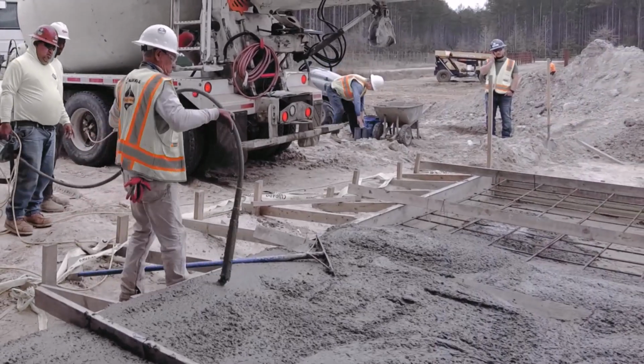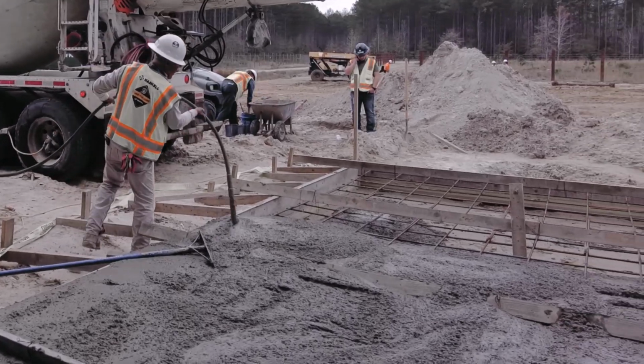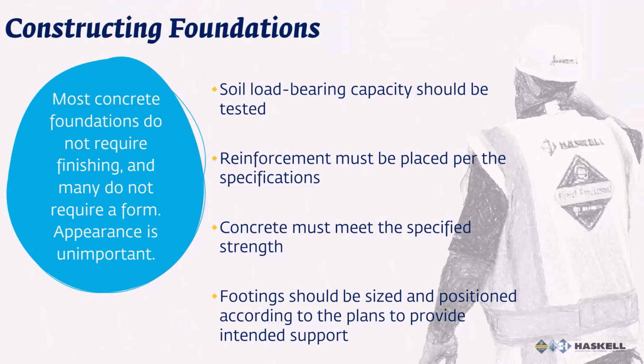Concrete foundation work is different from placing and finishing slabs. Since footings are normally below grade, their appearance is not important. There are 4 primary considerations in the construction of foundation footings. The soil load-bearing capacity should be tested and determined before placing concrete.